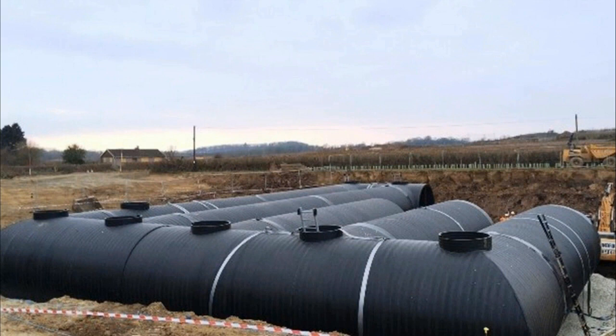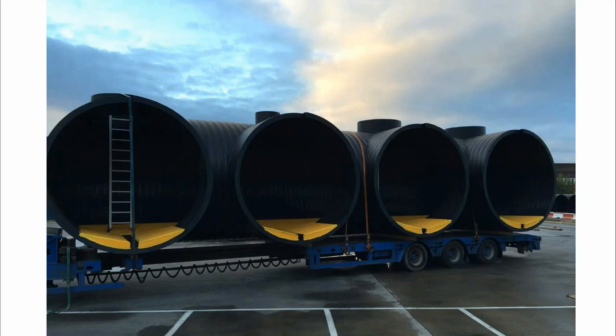When site footprint is limited and large volumes of storage are required, we can often get additional volume of storage between the pipes using the same diameter manifold configuration you see here. If you have available site and don't need that additional storage, usually bulkheads and small diameter manifold connections, hydraulic connections between the bulkheads is usually more cost effective, but it's very project specific and dependent upon the available footprint and volume of storage for the job.